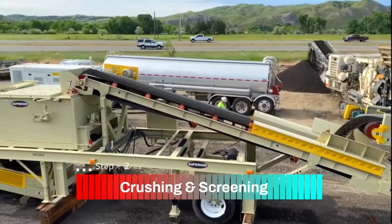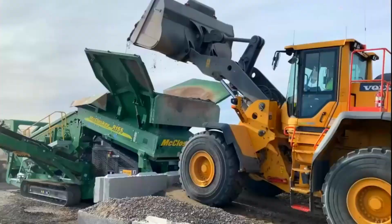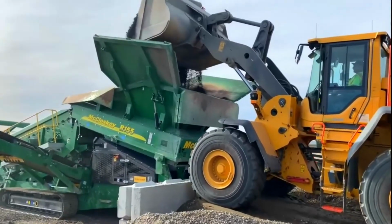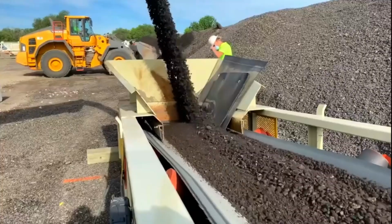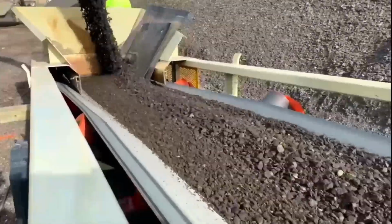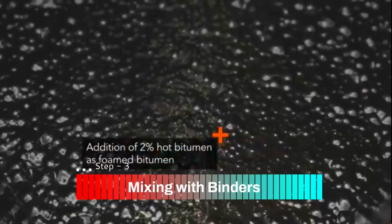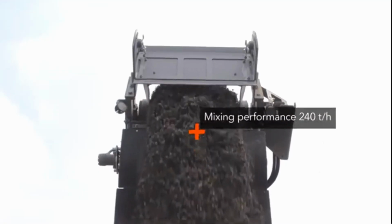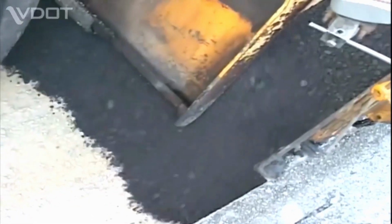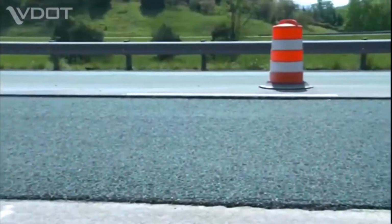Step 2. Crushing and screening. At the plant, the material is fed into a crusher to break down large particles. It is then screened to remove fine particles and achieve proper grading. Step 3. Mixing with binders, bitumen or cement. Bitumen emulsion, typically 2 to 3%, is added to improve binding properties. Alternatively, cement, 2 to 4%, can be blended for added strength. Water is added to achieve the correct moisture content.